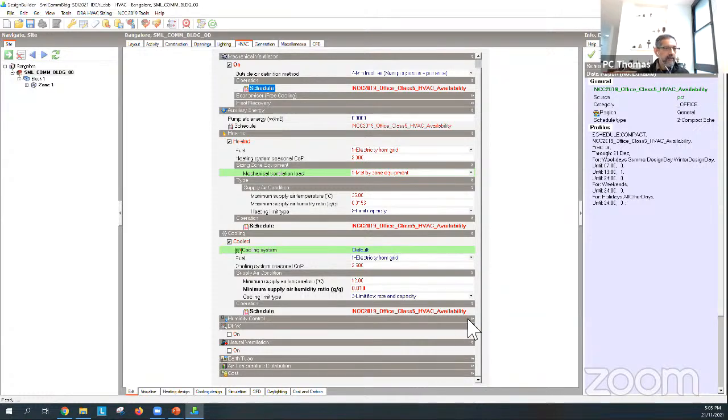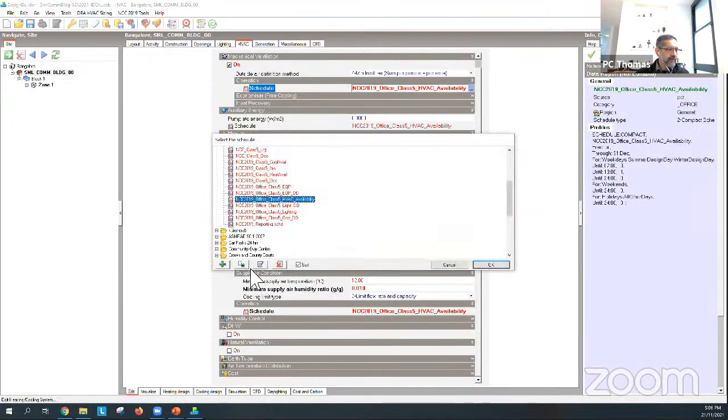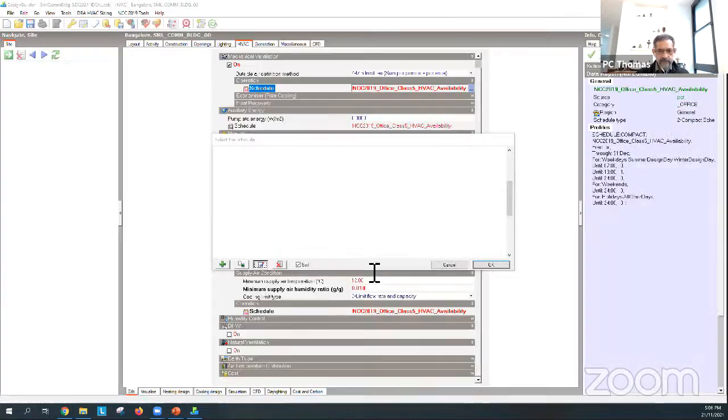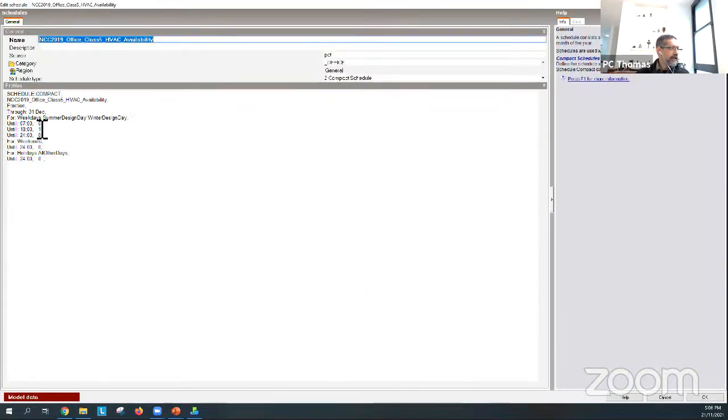Now, when you build schedules, you must be very careful about the type of the schedule that you're using. And I recommend that for the availability schedule, you use the fraction schedule. You have temperature, fraction, any number. There are some different types of schedules.